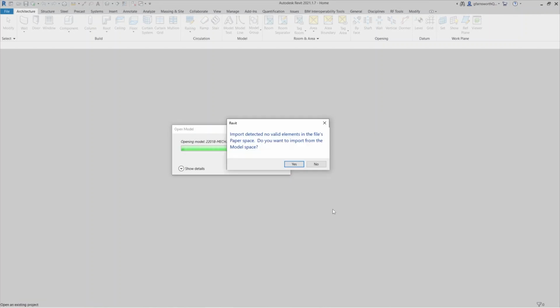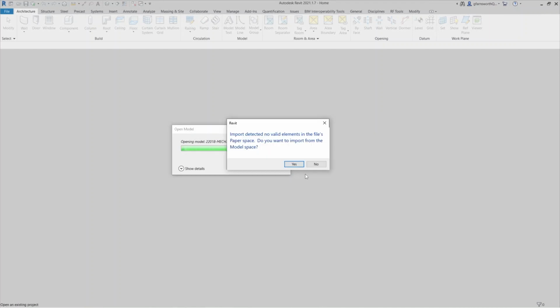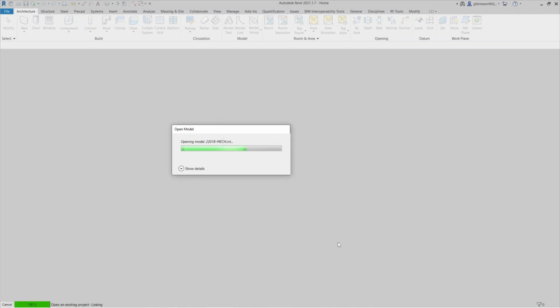Revit lets you import items from paper space into a view after it shows you the warning. However, Revit will show you the same warning dialog box for every AutoCAD file you link incorrectly. And it will show you all of those dialog boxes every time you open Revit. And it will show those same warning dialogs to everyone who opens a model linked to the models with the incorrectly linked AutoCAD files.